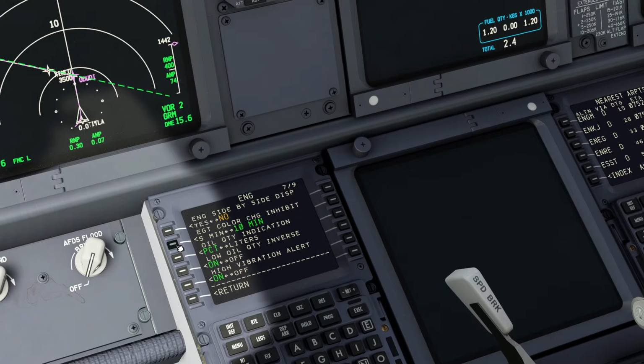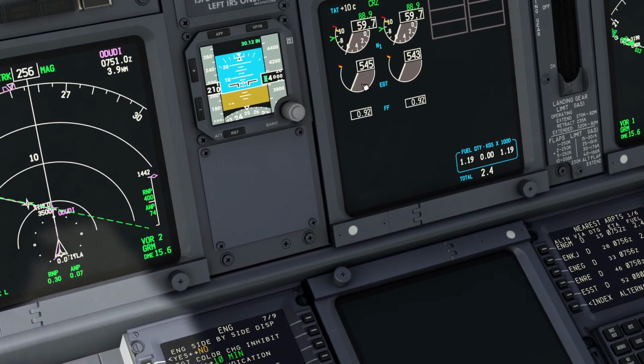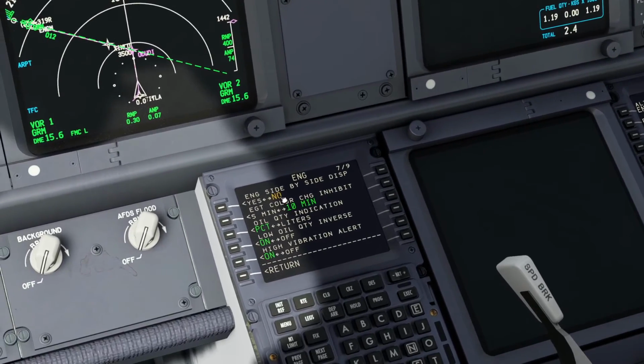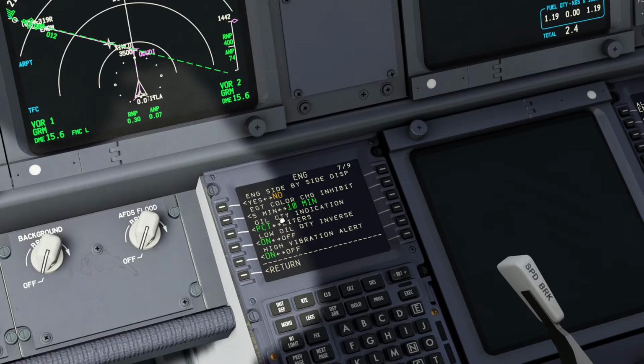So that's why, changing 5 to 10 here, if you never reach the EGT limit during takeoff, it will not change anything for you. Basically, the engines are certified for 5 minutes. And the engine manufacturer allowed the buyer of the airplane, the company that is buying that airplane with that specific engine, to extend this inhibit from 5 to 10 minutes if you are single engine.